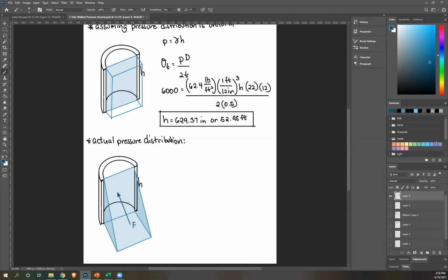Let's use violet. And it's going to resist along the sides because your force is here. So therefore, the area that's perpendicular to that is the one resisting. So it's these two. So it's going to resist like so. Okay? So we'll call that P again, because again, that force is actually tangential. Okay?